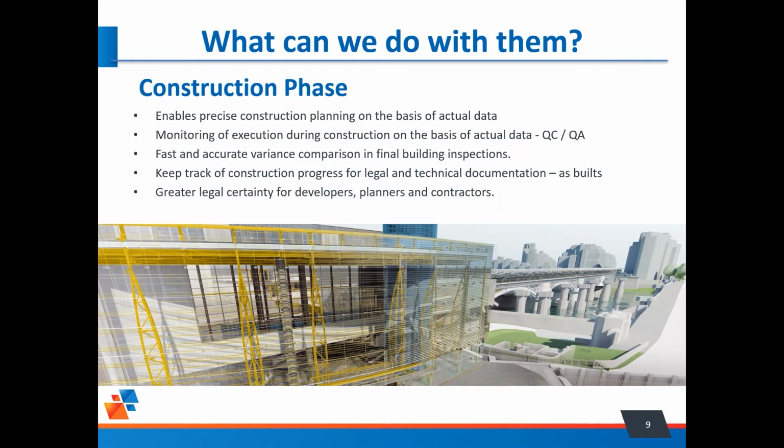You can also share this information with everybody once you create the point cloud. So if you say, okay, I'm going to go to site every week and take a scan, then we're always going to have that information to go back to or to forward on to all the stakeholders to say, okay, this is what happened on this day, this is what happened on that day. If there's ever an issue, go back to that day and say, oh, look at that, there was the issue, and we can see what happened at that time. Maybe before you put the board on, or before you poured the slabs, or maybe even before you have to core drill somewhere to make sure you're not going to hit a conduit.